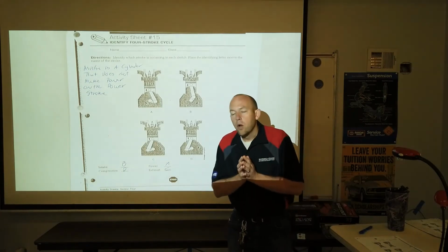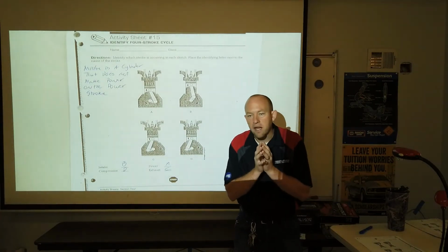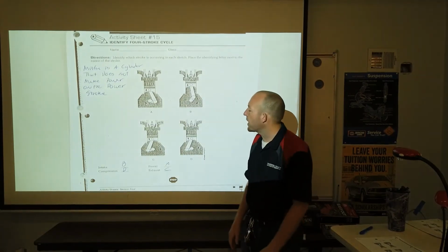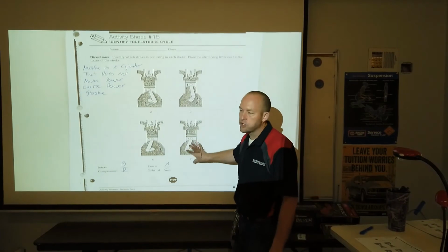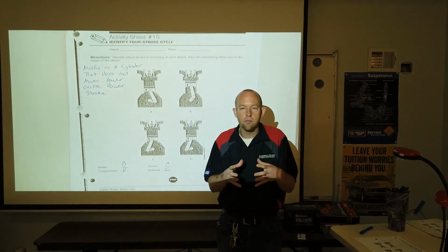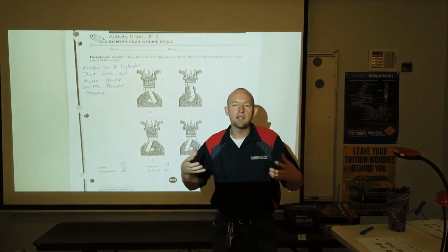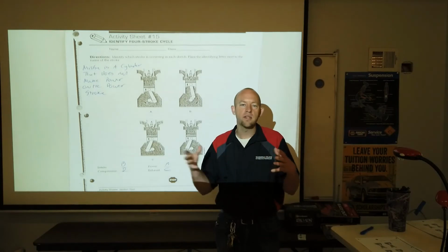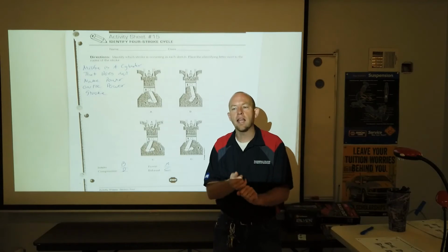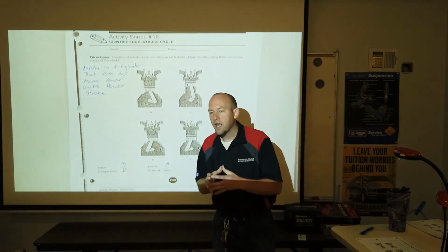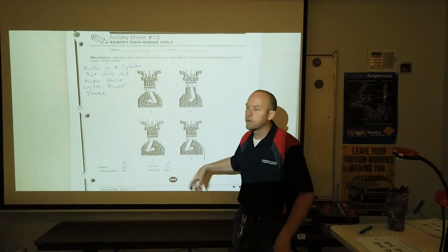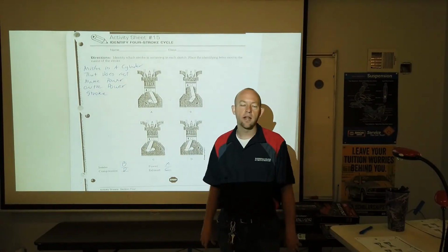Next, if I have a mechanical failure and I can't make compression, then obviously that affects my compression stroke. On my compression stroke, I have to be able to compact that air-fuel mixture down into a small volume. I always mention this to all my classes, this is the rule: if I cannot compress the air-fuel mixture, I cannot light it. If that air-fuel mixture is not compressed on my compression stroke, then I cannot light it, and therefore I end up having a misfire again.